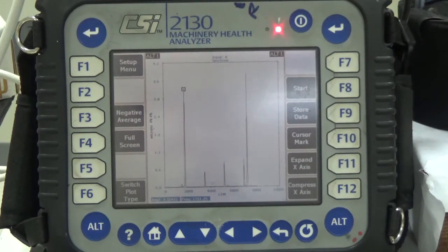But for finding the fault in the machine, you should also know the RPM of the machine, and you should know what the parts inside the machine are and what frequency they will generate. So you have to calculate the frequency of each part inside the machine, which it will generate in case of fault. So the spectrum is a very useful graph which tells you about both the fault in the machine and the amount of fault, or condition of the machine. In the spectrum, the amplitude is telling you the amount of vibration, and it is also telling you the severity of vibration.